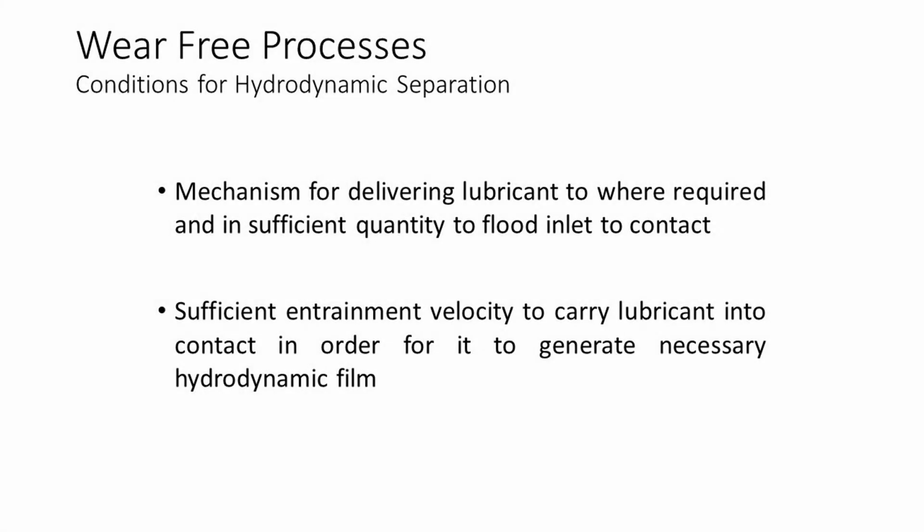A good starting point is to consider those real processes in which we would not expect wear to occur. We can then consider those processes where wear and failure does occur and try to identify the reasons why. Providing we have a clean lubricant free of abrasive particles or wear debris, with a contact operating under fully hydrodynamic or elasto-hydrodynamic conditions, and providing complete separation of the material surfaces, we should not expect to generate any wear.